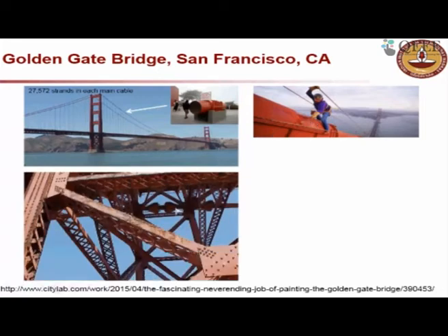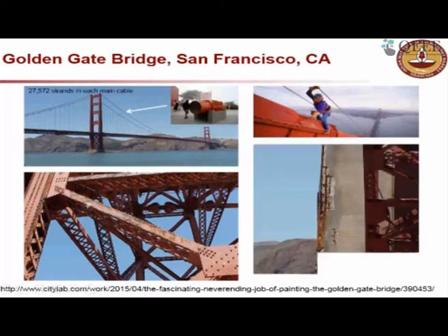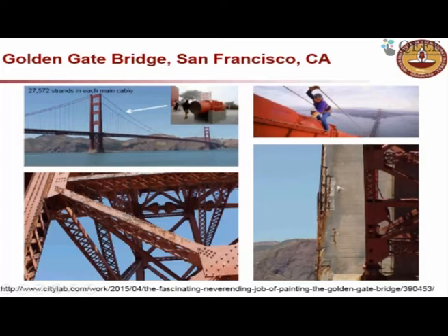But when you look at the steel trusses over there, you can see a significant amount of corrosion here. And if you look at the concrete elements of this bridge, there also you have a significant amount of corrosion. So even though the structure looks very good and nice from far away, when you go closer, you see that a lot of issues are there on these structures.